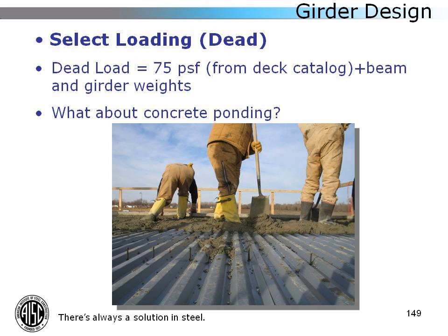But you also need to be cognizant of this issue of concrete ponding. If you're placing concrete, the beams are going to deflect. The girders are going to deflect. You're going to get some small deflections within the deck. And if you tell the contractor to pour the slab up to a certain elevation, there are going to be sections that are thicker than your nominal thickness. So you need to apply a little extra load in order to handle this concrete ponding issue.